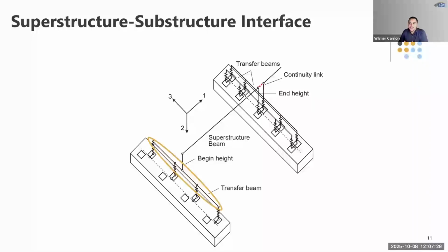The reason is that we want the transfer beam to transfer loads in proportion to the motions at the superstructure level and get a good distribution of bearing reactions, again, given that we're working with the simplified spine model. In short, the vertical link marks the center of gravity of the spine model and brings the loads down onto the transfer beam, and the stiff transfer beam spreads the loads onto the bearings.